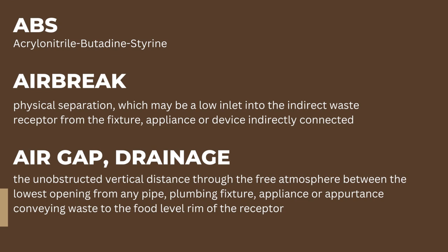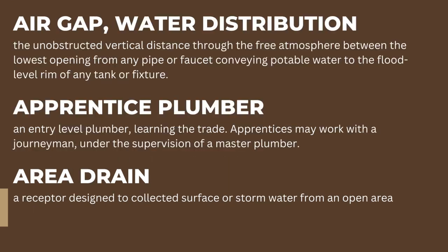Air brake. Air gap in drainage. The unobstructed vertical distance through the free atmosphere between the lowest opening from any pipe, plumbing fixture, appliance or appurtenance conveying waste to the flood level rim of the receptor. Air gap in drainage.